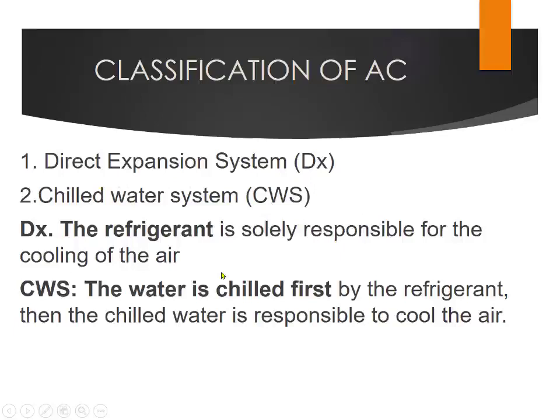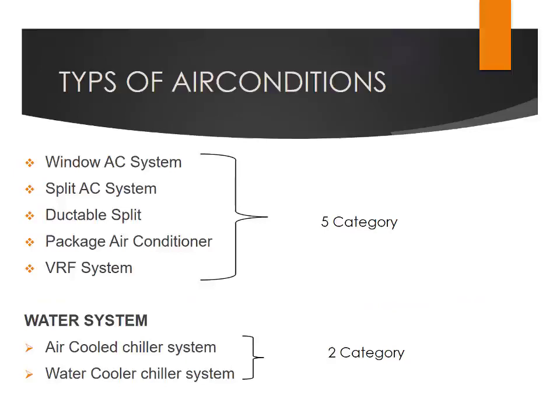Then the chilled water system. There's the introduction of a chiller. The water is chilled first by the refrigerant in the chiller, and then the chilled water is pumped into the air handling units. The chilled water is now responsible for the cooling of the air.